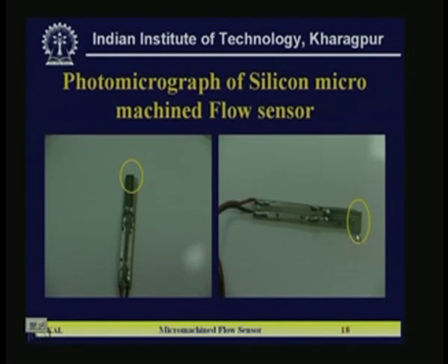The tip is a different color, which is the nickel, and the rest of the line is gold, and that is soldered to a small PCB, so that you can cover the whole thing in a tube, which is fitted in the measurement chamber, the measurement setup. Here also is structure 1, where the tip is the nickel resistance. So, these are the fabricated devices.